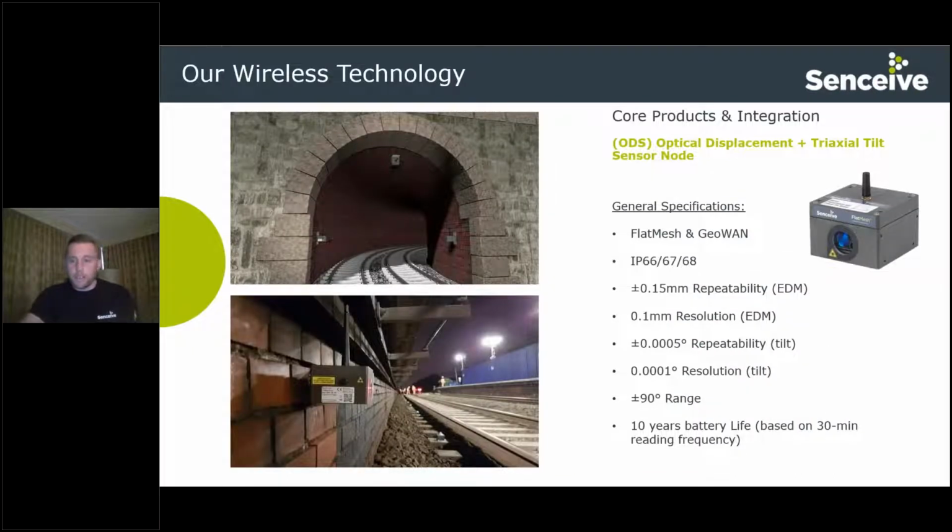You can take that same triaxial tilt sensor and add a distance laser measurement. So what you can do with this, in the top left, this is inside a tunnel arch where you can actually measure the lateral distance along with the 3-dimensional tilt. So you get those tilt readings plus a distance measurement. So it's a very powerful tool to be able to determine what's happening with structures like this. And I'll actually show a case study later of that top picture where they actually use these sensors to determine the lengths and come up with the chords of that tunnel.